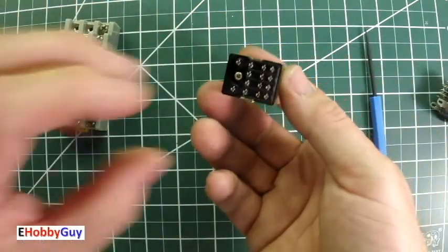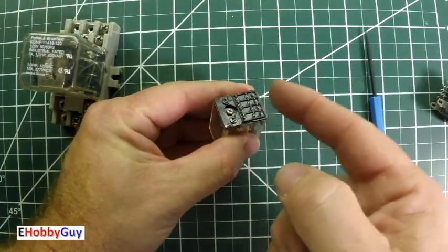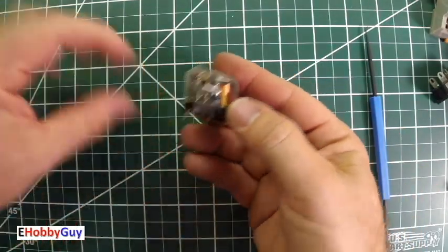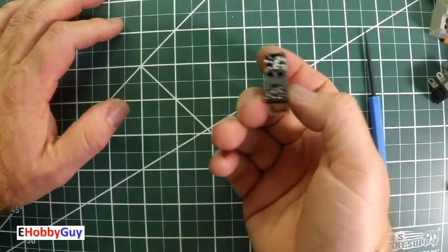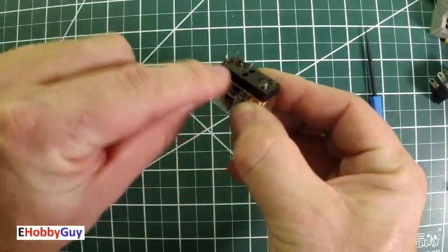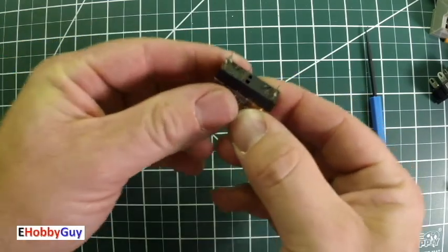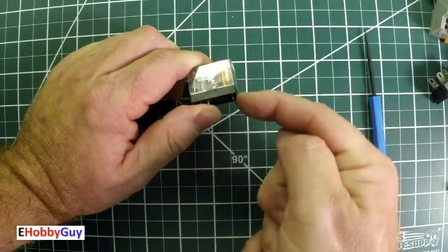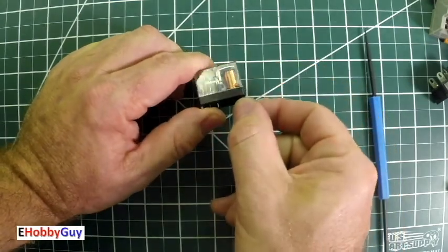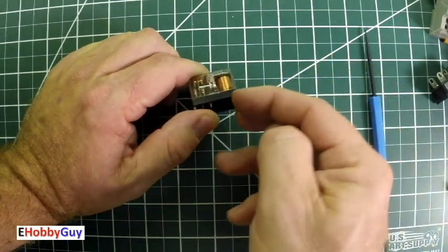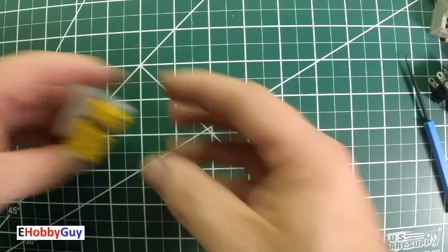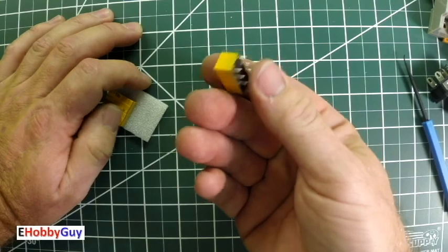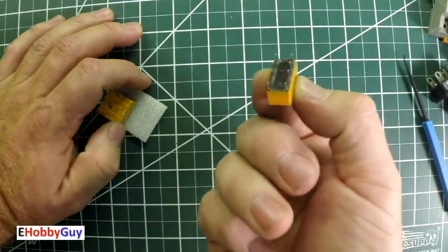And looking back really quickly, anything, as we know, that is a common, normally open and normally closed, is a Form C relay. This one you can see into pretty clearly. Once again, it's common, normally open, normally closed, which means it's a Form C, double pole, double throw. And this is the coil. Another thing, you can just physically see that coming down from the coil will be the contacts that are used to energize the coil. Again, here's some PCB mounts that I had lying around. These are very typical double pole, double throw Form C relays.